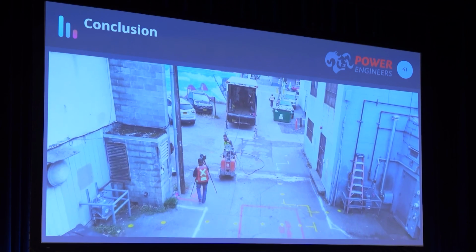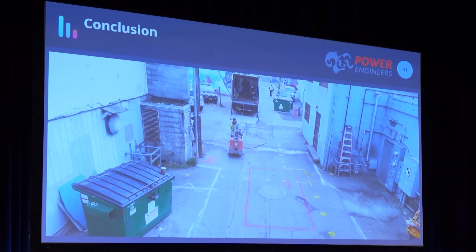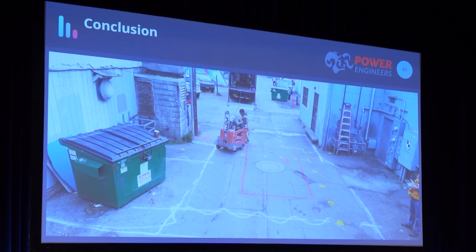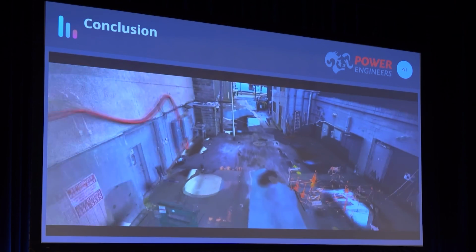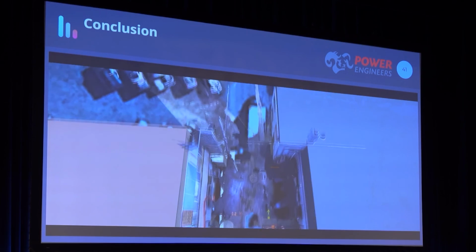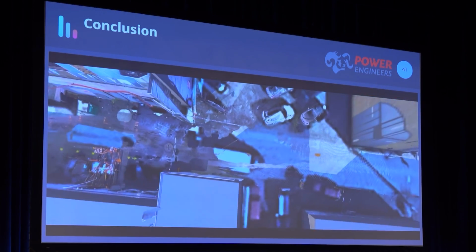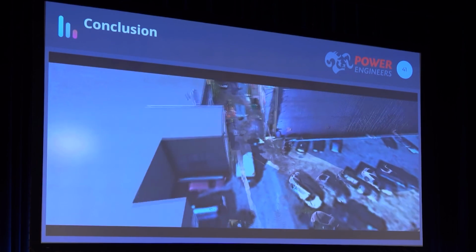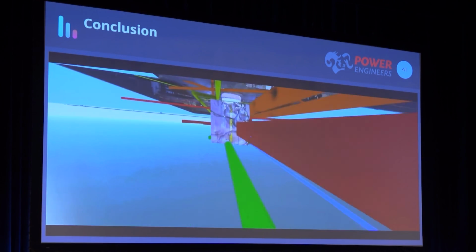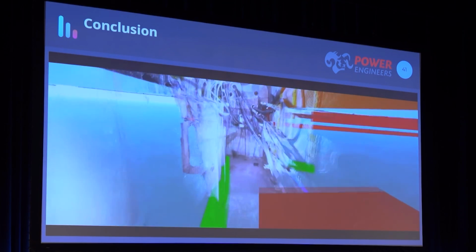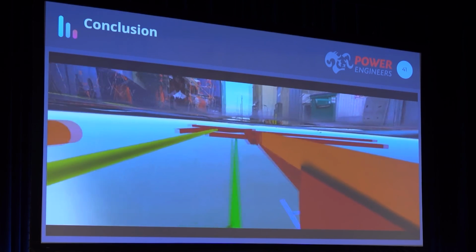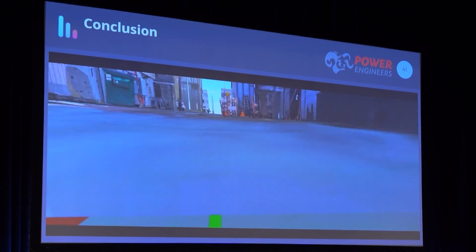So this is a video, it's a vault model we talked about. The end value is when we do use reality capture, we can have real-time information. The workflows and processes need to support that we know what's existing at any given time. We've used vault scans for inspection. We captured them for design and for asset management. But inspectors who needed to verify asbestos fire tape could look at our vault models and identify the absence or presence of asbestos fire tape without road closures, without entering confined space, without entering a high voltage situation. We can model the existing utilities around those to do engineering design and analysis.